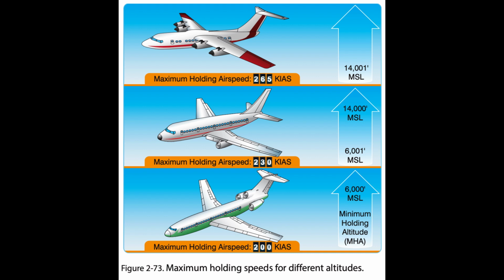For flights scheduled for more than 1 hour, the pilot may record the time and fuel remaining shortly after TOC and at selected waypoints listed in the flight plan, conveniently spaced approximately 1 hour apart. The actual fuel burn is then compared to the planned fuel burn. Each fuel tank must be monitored to verify proper burn-off and appropriate fuel remaining.